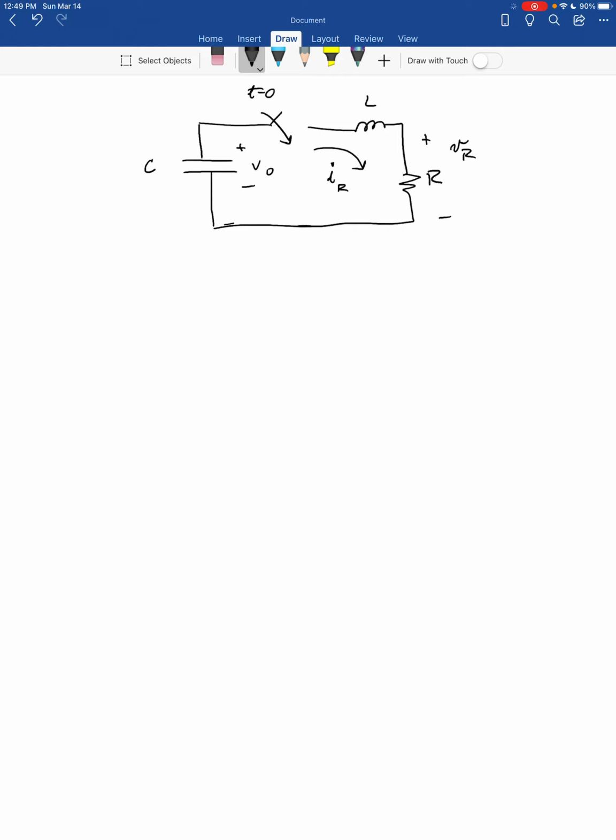In actuality, in pulse power, this is usually the first stage in several power conditioning stages where they tend to get higher and higher peak power and shorter pulse duration. So a lot of times this is just kind of the initial power conditioning that then feeds maybe something else that shortens the pulse even further. But the fundamental thing of storing energy capacitively is fairly common. Capacitors are cheap. They can be built with very low leakage, and so you can hold this DC voltage for a while on that capacitor and then release it.